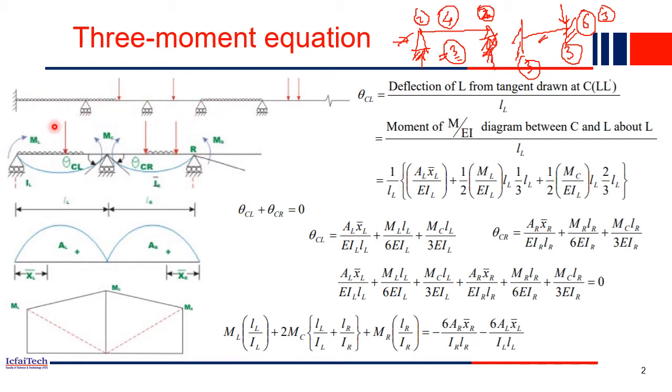So this is a very real problem, real life. If you see, all the beams are actually continuous beams, not single beams. Unlike this one, our real structures are actually continuous beams, and the structure is also indeterminate, highly indeterminate in nature. But till now we discussed how to solve determinate beams, that is simple structures. So today we'll employ the three moment equation to solve continuous beams.